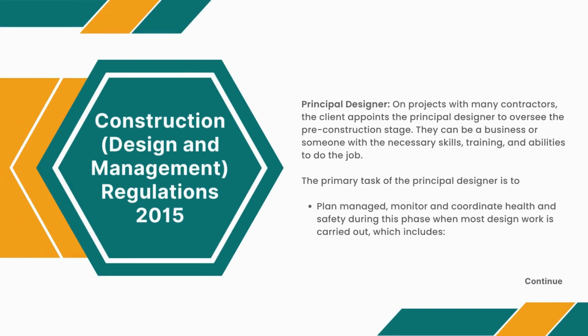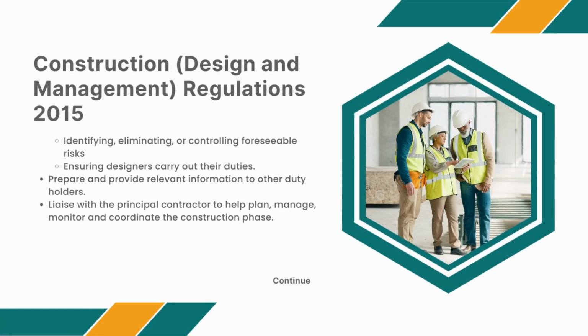Principal designer. On projects with many contractors, the client appoints the principal designer to oversee the pre-construction stage. They can be a business or someone with the necessary skills, training, and abilities to do the job. The primary task of the principal designer is to plan, manage, monitor and coordinate health and safety during this phase when most design work is carried out, which includes identifying, eliminating, or controlling foreseeable risks, ensuring designers carry out their duties, preparing and providing relevant information to other duty holders, and liaising with the principal contractor to help plan, manage, monitor and coordinate the construction phase.